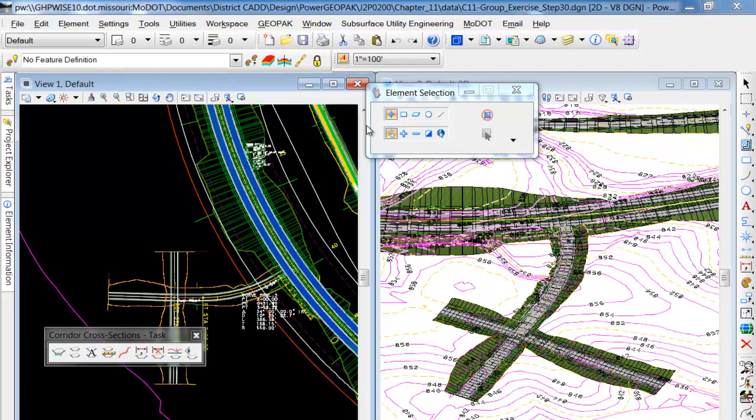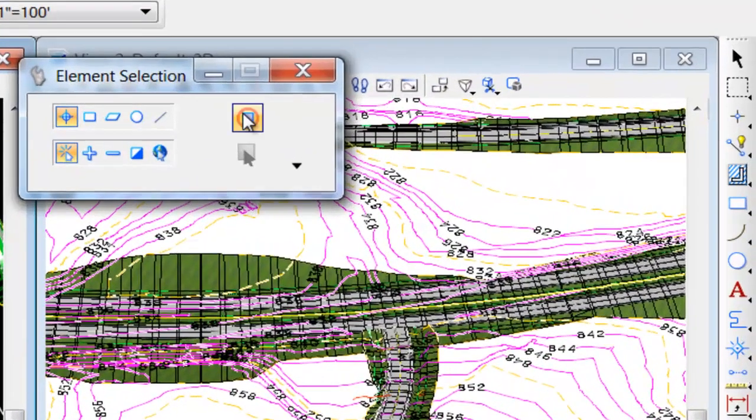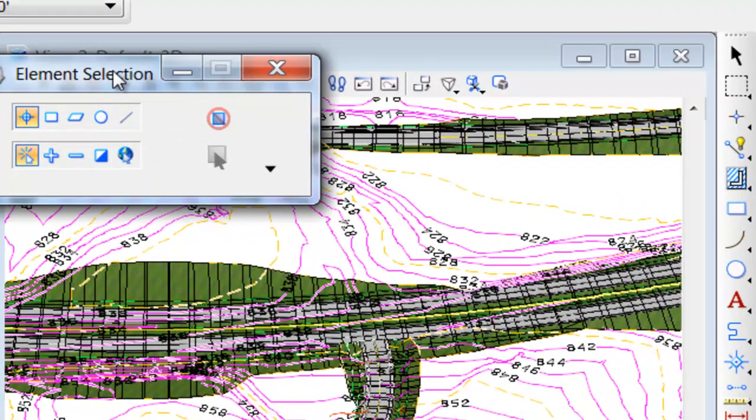It goes in and talks about setting the terrain model active, which we've done in previous chapters. It goes in and draws in horizontal alignment, and in this particular drawing, it uses that existing ground as your vertical alignment. Out to the left-hand side of this drawing, there is an existing roadbed already there, and we're going to place a roundabout at an intersection out there.